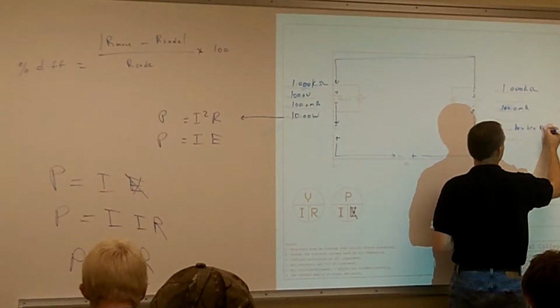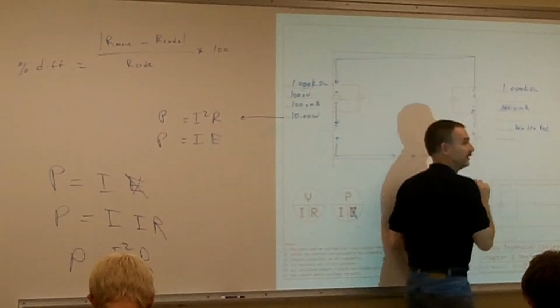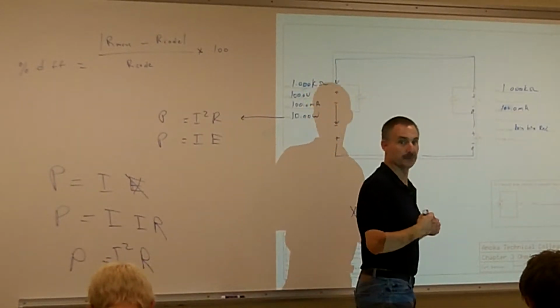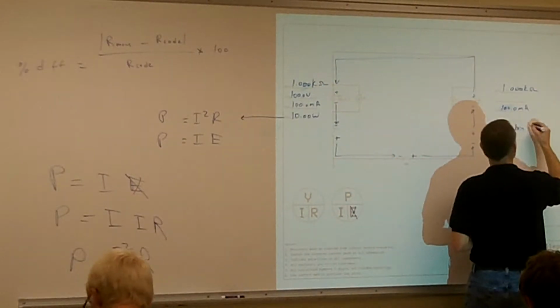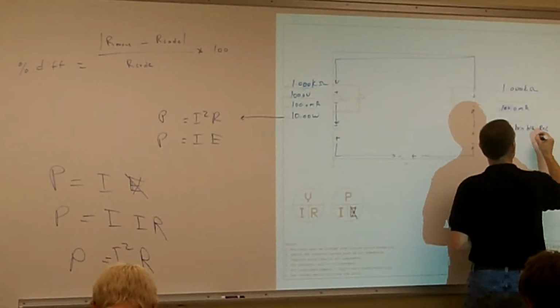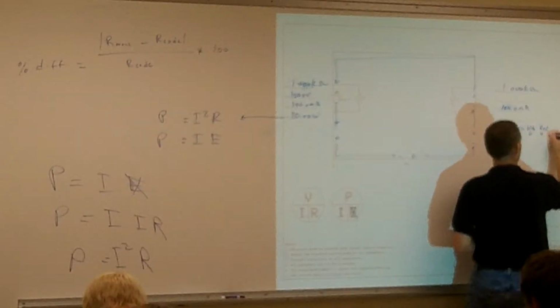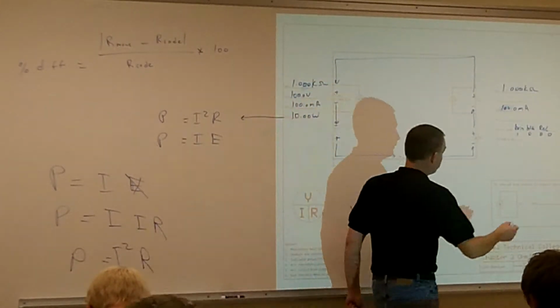Brown, red? Brown, black. Oh, brown. Yeah, you're right. Brown, black, red. Yeah. Black is 0, so it's brown 1, 0, and then 2 more zeros, 1, 2. Yep, so brown, black, red, and then we know it's gold.